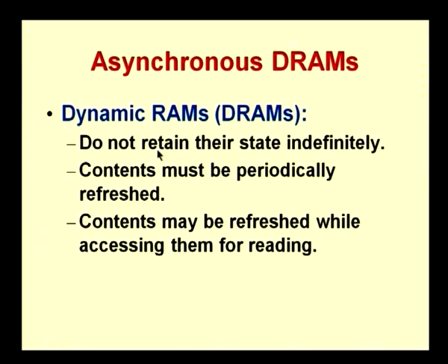Another type of RAM that we use is what is called a dynamic RAM. The moment we talk about a static something, dynamic will be something slightly different from that. So let's look at what a dynamic RAM will be. The basic difference is that dynamic RAMs will not retain their state indefinitely. We said that a static RAM is a volatile memory, and once you switch off power, it will lose the data. But if you do not switch off power in a static RAM, whatever data you have written will be held in that flip flop forever as long as power is maintained.